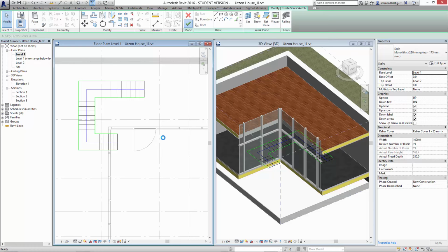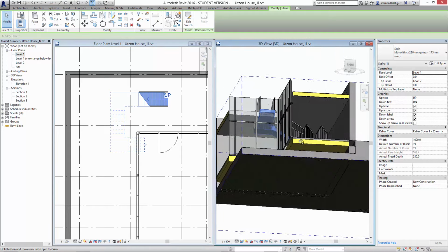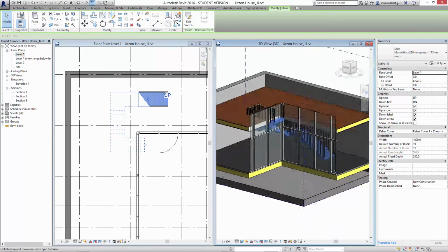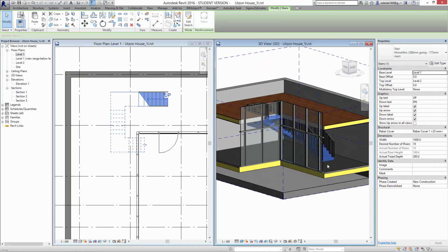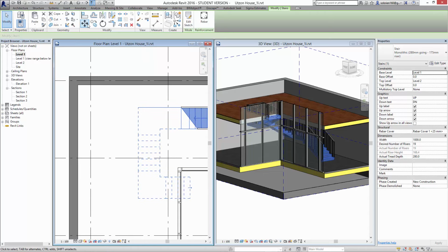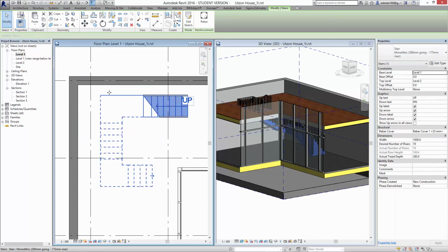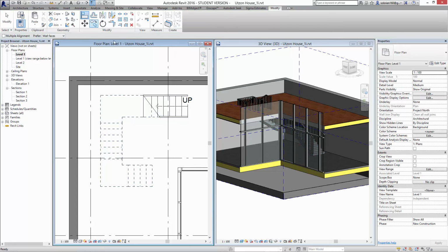And it generates the stairs in 3D. So you can see the stairs in 3 dimensions over here. It defaults to a concrete stairs with a handrail on both sides. Once you've made it, you can take the stairs and move it to the correct position. You can either use the move tool by taking the corner of the stairs and moving it to the corner wherever you want to put it, or you can use the align tool to align the stairs directly to a certain position. Oops, that was the handrail. I didn't want to do that. Let's just use the move tool today. Move, corner.